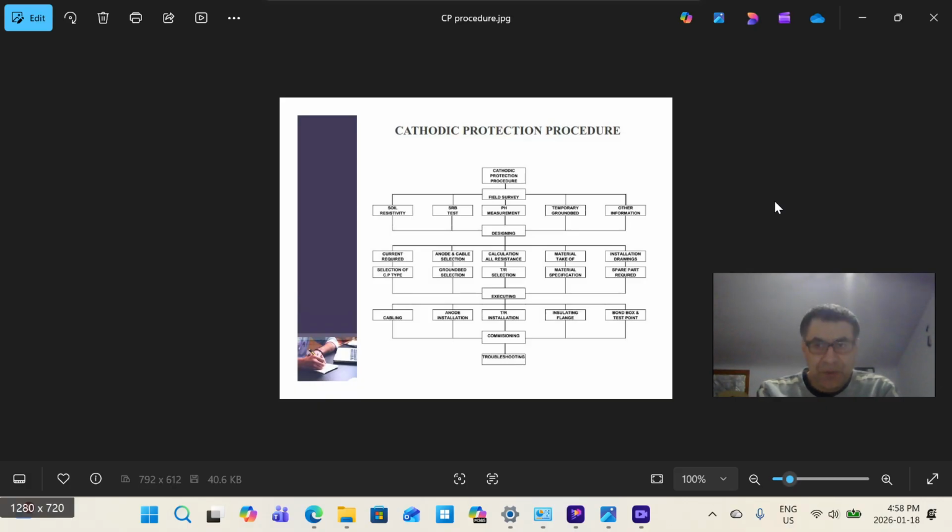pipeline operation people. And during the operation, as I said, we need to analyze the data. We need to review the condition of the underground pipeline to make sure it is continuously protected by sacrificial anode and the cathodic protection is intact and functioning properly.